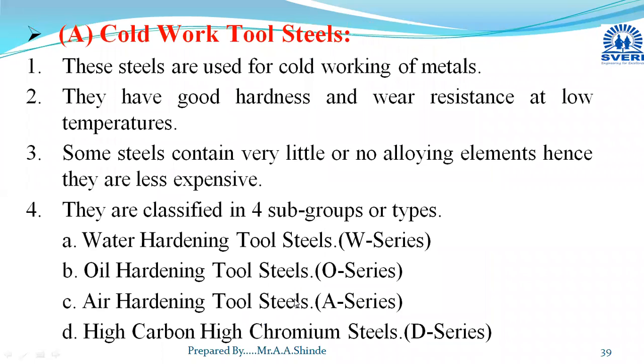Now, in this slide, I have highlighted some specific characteristics of cold work tool steels and their classification. These cold work tool steels, as I have already explained, are used for cold working of the metals. All four subtypes of these cold work tool steels have common characteristics: they have good hardness, toughness, and wear resistance at low temperatures.